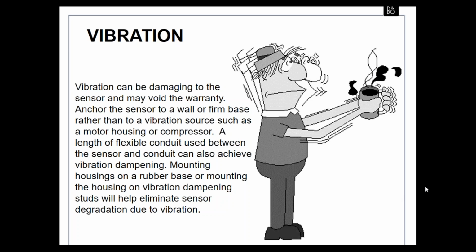stand right next to the pump, the beads lasted two to three years. Also, compressor stations. We have many units in compressors. I think it's at Walt Disney World in Florida, where they generate their own electricity using turbines. In the original installation, they were mounting the sensors in an area where the frequency of the turbine was vibrating the sensor enough that the sensors didn't last as long. They lasted about a year before they gave way. So again, vibration is very important.